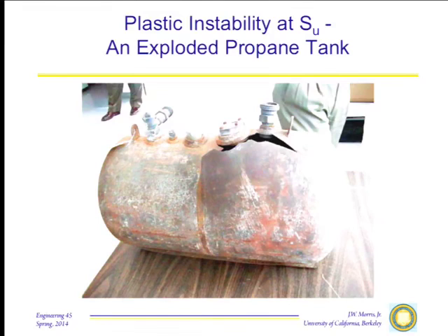One of the interesting things about explosions like this, I don't want to kill too much time today, but there are two kinds of explosions. It's very, very important to keep in mind. There are hydrostatic explosions and there are pneumatic explosions. By looking at this, one can immediately tell it's a hydrostatic explosion. This happened because the tank was overfilled with propane. Turned out there's a safety valve in the tank, the guy welded it shut because it was causing problems. And then it was overfilled with propane on a hot day, so the liquid expanded, boom, there goes the tank.